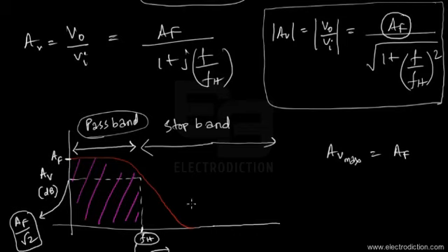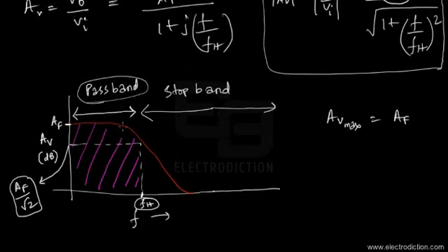Okay, so there you go. And now if we look at the curve over here, you can see that near FH, that's the upper cutoff frequency, the curve just rolls off, it just dips down. This dipping down tendency of the curve is just referred to as a roll off. So this entire region is just referred to as the roll off of this particular curve.